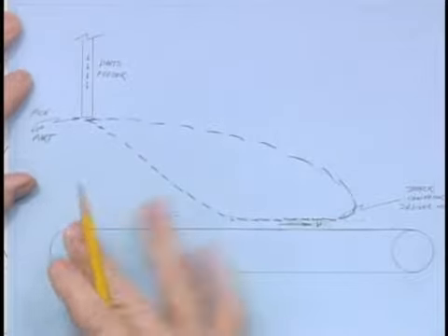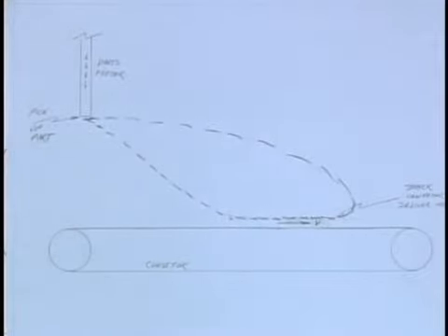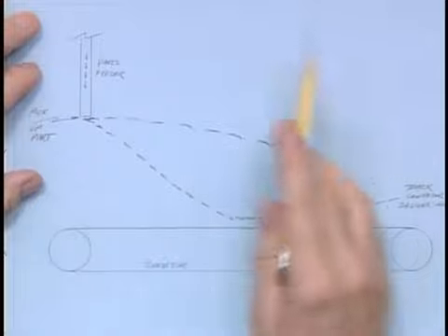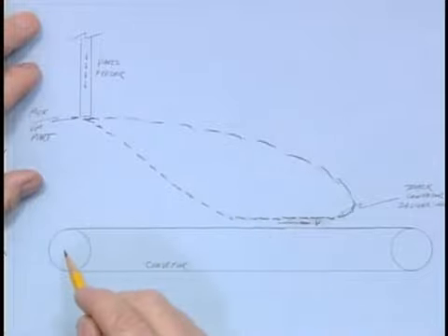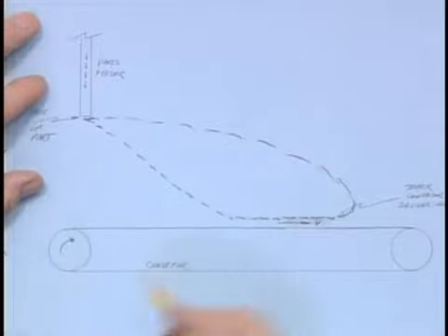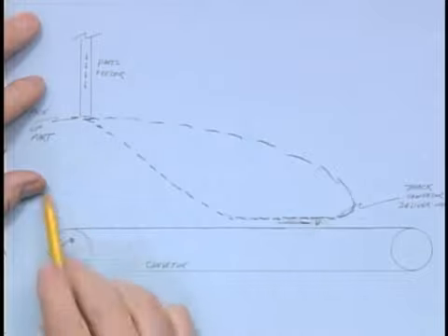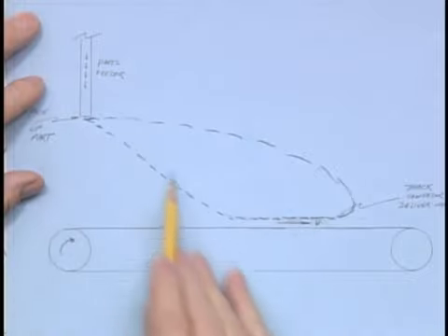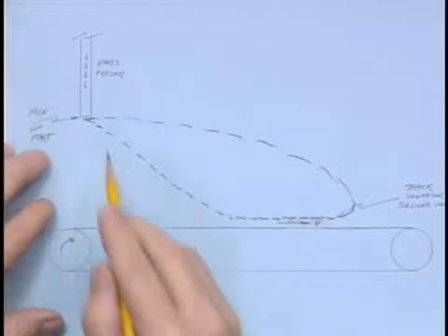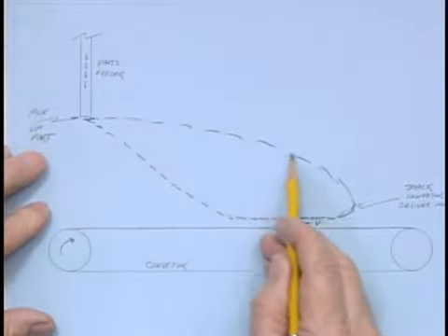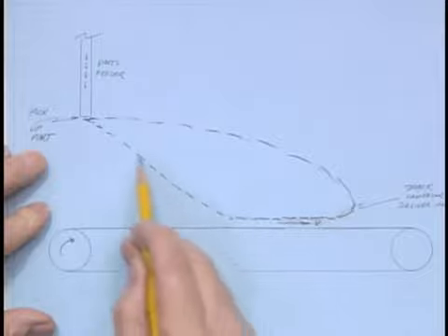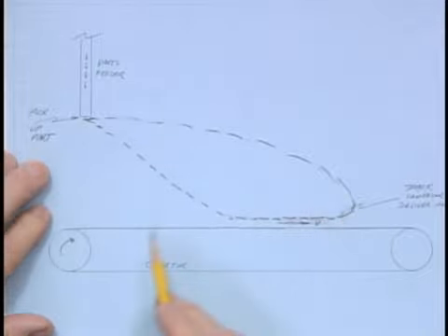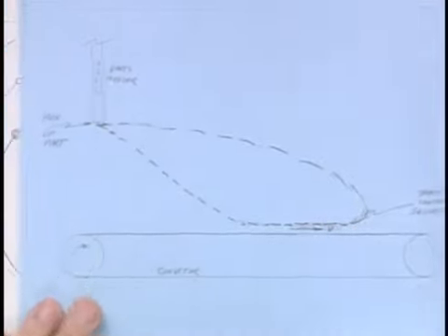So this, my linkage, which is not yet shown here, that's what I'm trying to find, is going to be driven by the same motor that drives this conveyor, such that everything's in synchrony, so that as a part appears in the proper location here, as the nest appears, my part will also appear and be transferred. Okay? That's the idea. So I'm now looking for a curve that sort of looks like Willie the Whale here. Okay? I want to now go into my Hrones and Nelson atlas and see what I can find.